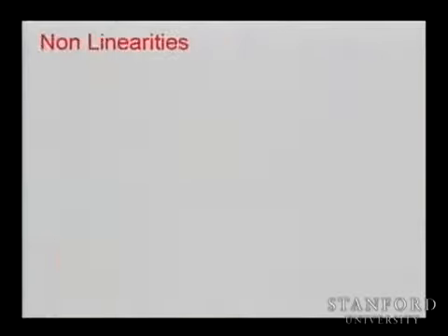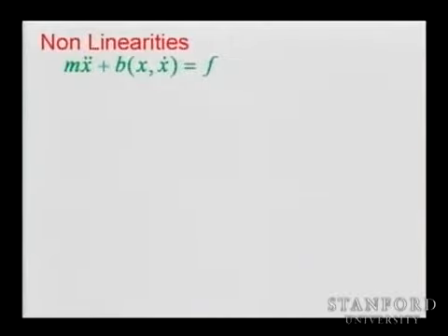Okay, now we are going to introduce one more element. We talked about it on Monday, and this is just a tiny nonlinearity. Let's add some friction. So we started with the system without any nonlinearity, and now I'm just adding a little bit of friction, nonlinear friction, like some stiction on that joint. So the equation changed completely. That is, it's not linear anymore. We cannot just treat it as a linear system, and we have to deal with a controller that is going to be nonlinear. So how can we deal with this? Come on, ideas.